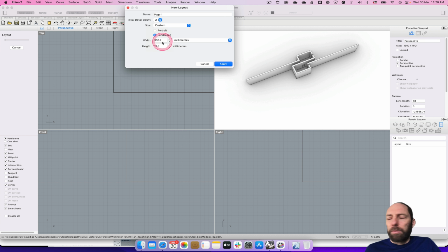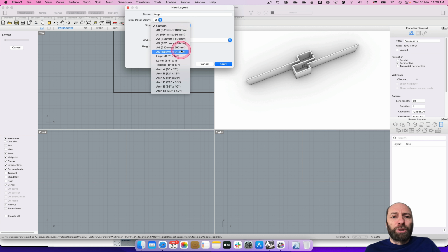we've got a landscape because we're doing the 16 by 9, and I've got this crazy number for you, which is 338.7 by, that's not right, 190.5 millimeters. And that's 16 by 9 in millimeters. Because we're just going to a screen, this is the right sort of proportion, so it uses up the full monitor that you'll be presenting on. But if you're printing to a piece of paper, you could create some like A4 or A3 layouts as well.